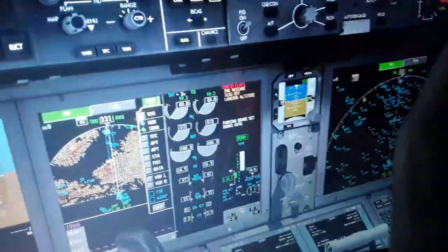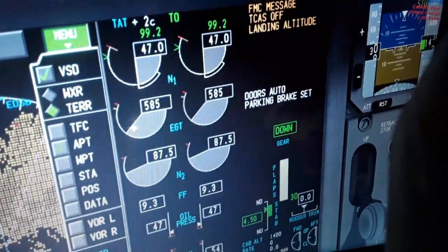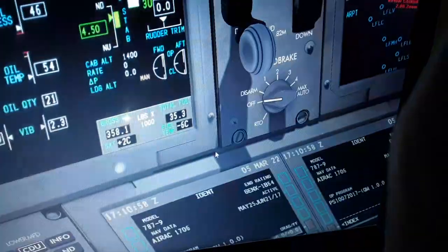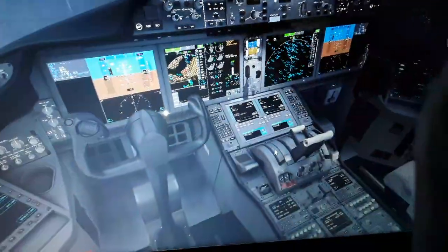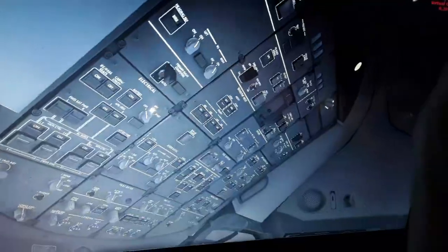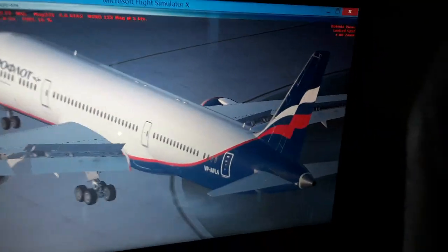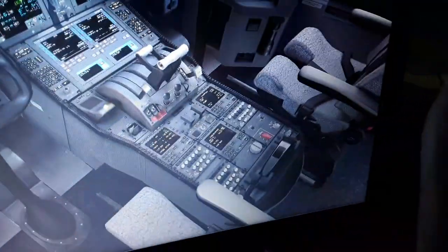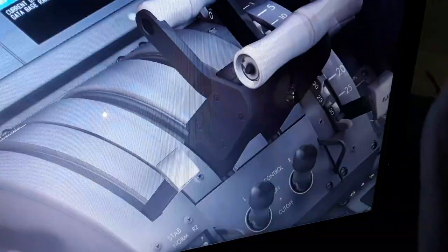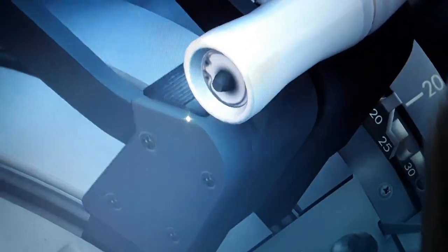I will not configure for takeoff. It will give us some warning, these red warnings in the display. We need to do something before going to take off. Select some items here inside the aircraft. So we have a few more minutes to complete all the systems and the explanations. So we have the left and the right engine. We have the auto throttle, very important. Disengage switch here, the takeoff ground switch, the thrust reverser.